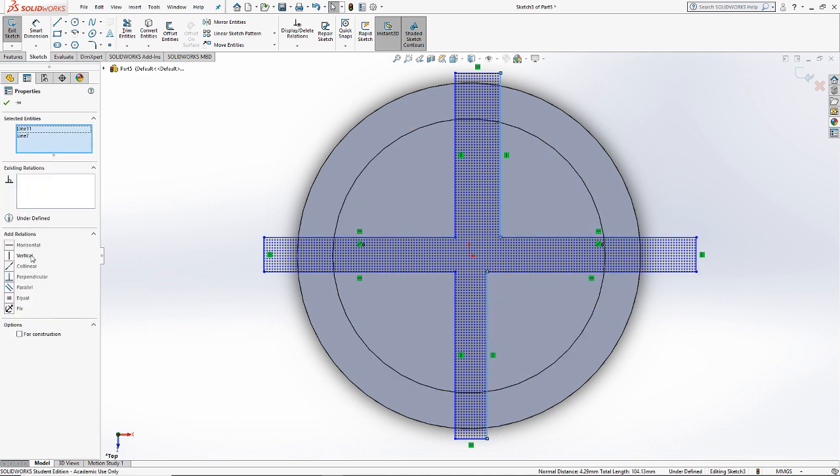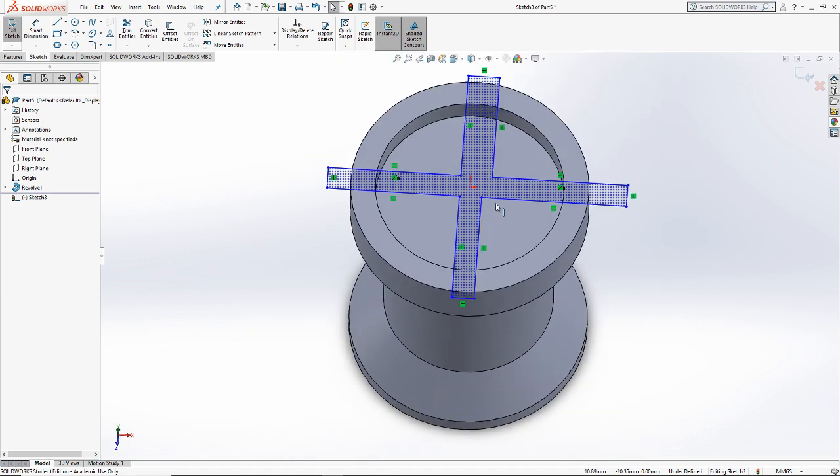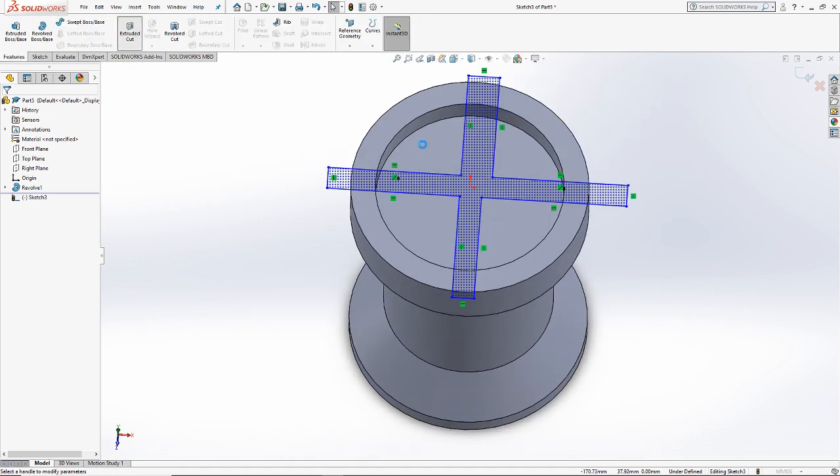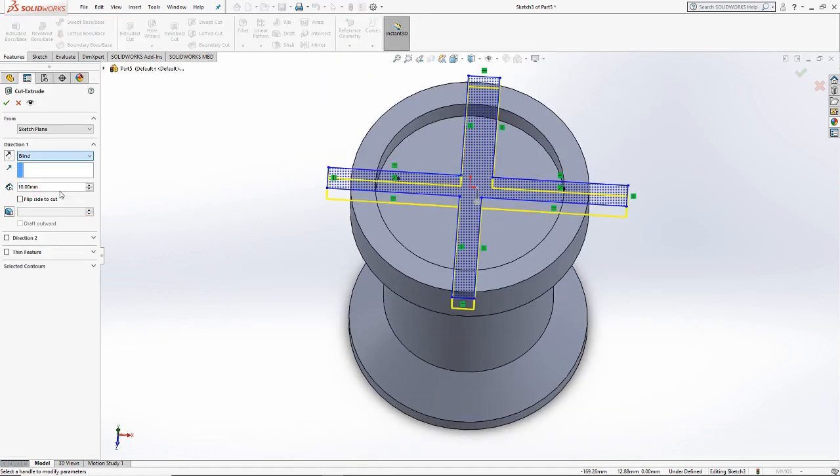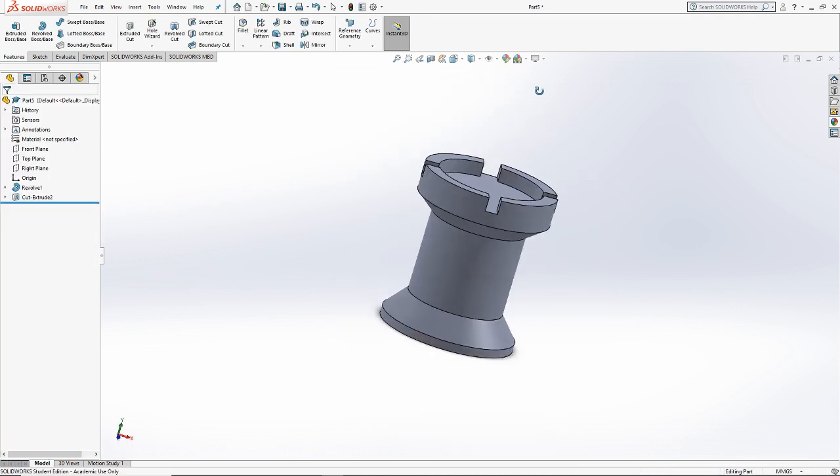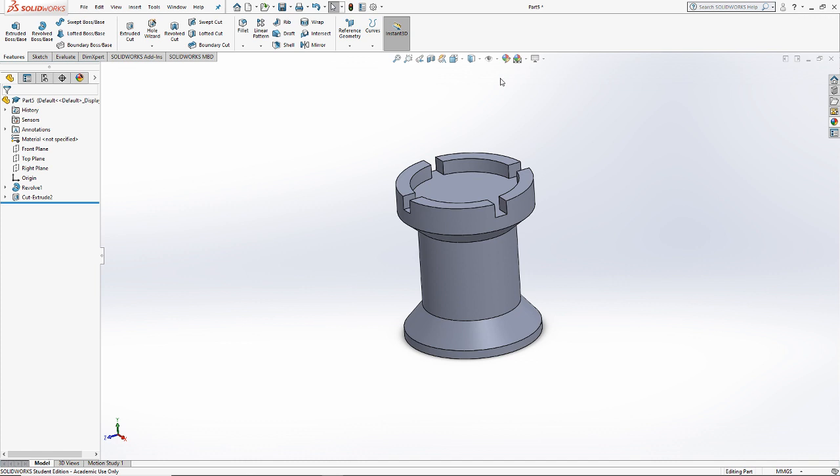Now, yeah, it's okay. It's just a very nice looking plus. Now when I use an extruded cut and cut down to a surface, I can select the top part of the inside of the rook and create those notches in one feature. I'm guessing you're about to ask if you could create a single cut and pattern it. You can totally do that, but we haven't officially covered the pattern yet. Does that logic make sense?